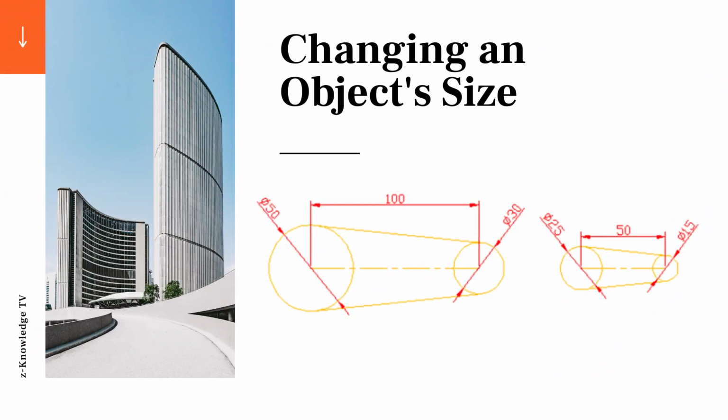So when you create drawings, it is often quicker to modify existing geometry than to create a new geometry from scratch. With the scale command, you can resize geometry to meet the current design requirements. Okay, so just like in these figures. So the object on the right was created by scaling the object on the left by 0.5 unit. So let's start in our sixth and last lesson in manipulating objects on how we can use the scale command.